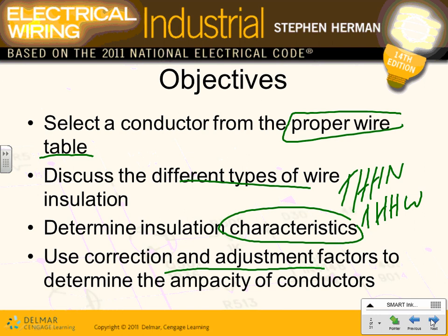Shoot that one, and there's another motor right next to it that also needs another 3 conductors, number 10. It's a very good idea to put these 6 conductors, number 10, with an equivalent ground conductor in one conduit, say 3/4 of an inch empty, and shoot them all the way to that location, to a junction box, land them there, and feed the two loads. That's where it makes sense to group things. Can I have thumbs up, chat, when it makes sense to group things?